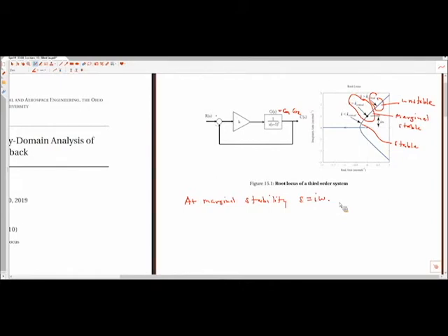Bode plots, right? Exactly. That's our standard substitution. S is equal to i omega. All right. So what this actually tells us is that by substituting S is equal to i omega, we can actually understand something about stability. That's what we're going to talk about here. So the Bode plot can actually give you information whether or not the system is stable or not. Right. Which is something that we always talk about. This is a responsive system to harmonic inputs, and that's definitely true. But there's also other uses for the Bode plot as well, and so we're going to use this to understand stability.